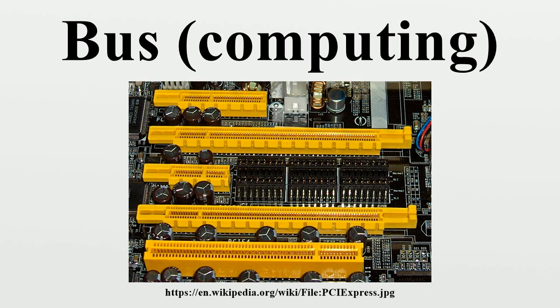Early microcomputer bus systems were essentially a passive backplane connected directly or through buffer amplifiers to the pins of the CPU. Memory and other devices would be added to the bus using the same address and data pins as the CPU itself used, connected in parallel. Communication was controlled by the CPU, which read and wrote data from the devices as if they were blocks of memory, using the same instructions, all timed by a central clock controlling the speed of the CPU.